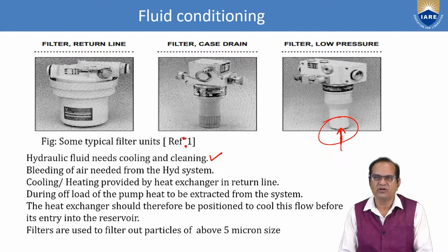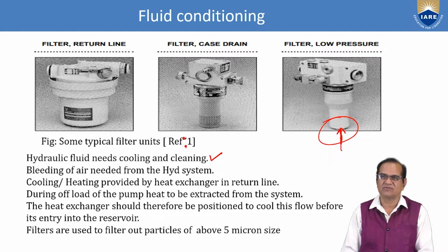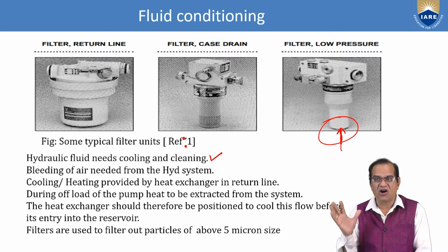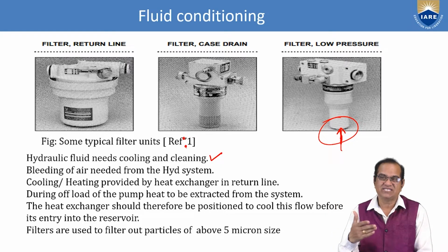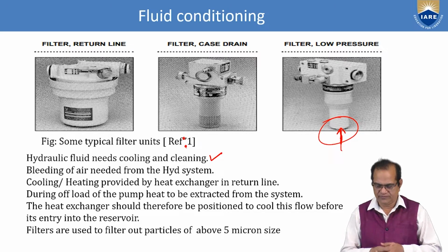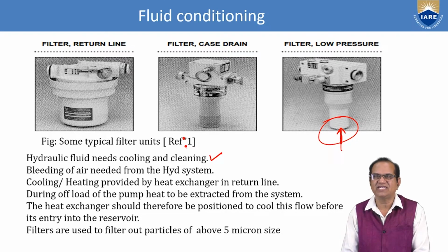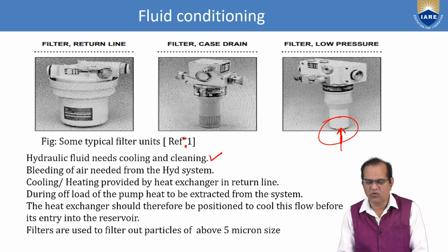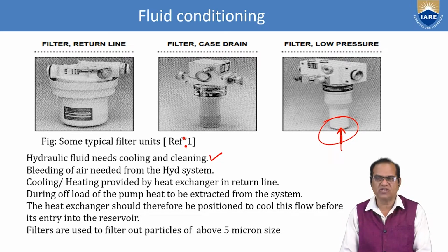During offload of the pump, heat has to be extracted from the system. So during the return line, or after the pressure is released, this has to be cooled. The heat exchanger should therefore be positioned to cool this flow before its entry into the reservoir.